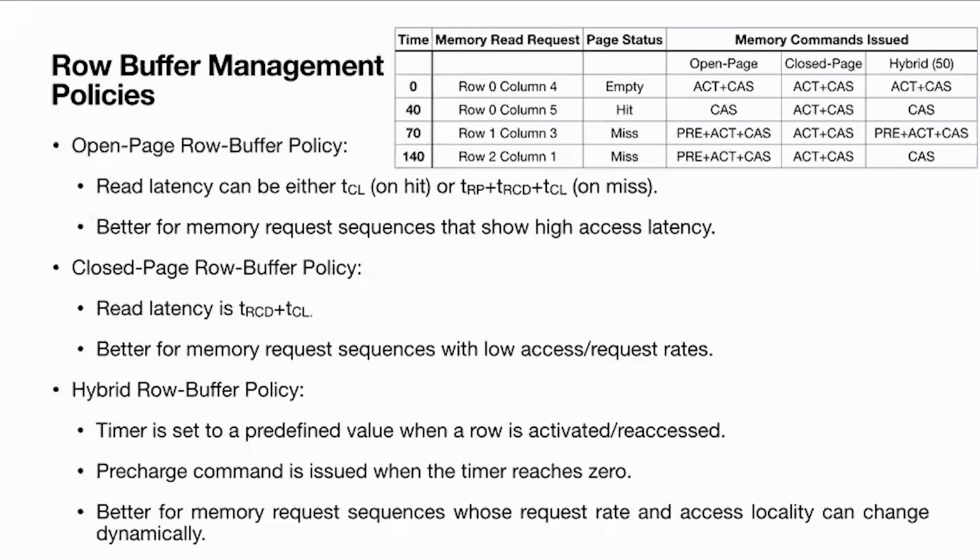Again, there are techniques. For example, there are mechanisms for reverse engineering the DRAM memory controller, to see what is actually implemented in Intel-based systems or AMD-based systems and so on. For example, there is one recent paper on attacks on DRAM-based memory. There they looked at Intel-based systems, I think Rowhammer-related stuff, where you can come up with attacks on the DRAM rows. But there they looked at reverse engineering the memory controller. It takes a good amount of effort to see what is actually implemented inside. But if you get that, then probably you can do something.